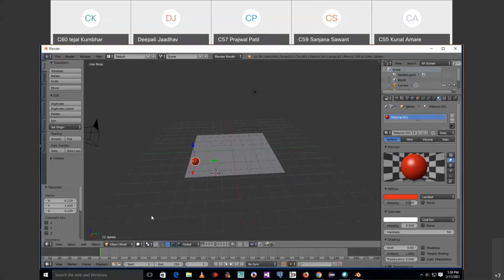Now for the addition of the keyframe. So here you can add the keyframe. First I am going to minimize this 250 up to 80. Okay. Next, keyframes means here one by one you are going to see the animation. So once you add the frames one by one, after completion of the animation, it will act according to the keyframes. Whatever activity you have done or given during that particular keyframe, that activity will appear when you perform the complete animation. So here first select the keyframe.